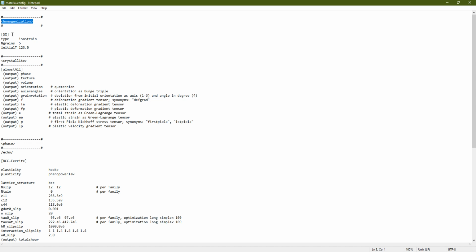So generally we have isostrain, which means it is equally divided on all the grains and orientations. This is correct and true for bulk materials, where the slip systems are more active than the grain boundaries. In those cases, isostrain is a very reasonable homogenization scheme. So how do I divide this force on every individual grain? Just resolve it with respect to the size of every grain.